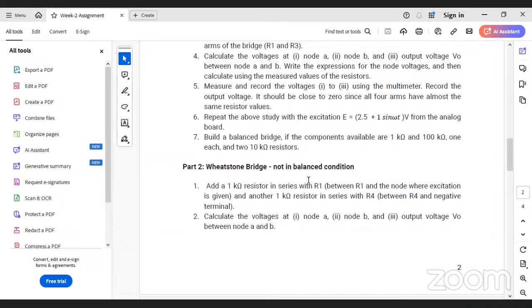If you add a sinusoid to a 2.5 DC, the lowest point will be 1.5 and the maximum point is 3.5, right? It will add and subtract one, like that. I'm not getting in Pixel Pulse where to give that, how to move the sine wave up and down. Okay, it's zero. Okay, 0 and 2.5 volts is mentioned along with the frequency. So there you can change it. Okay, one minimum point and maximum point. I think you just have to figure out how to work it. Okay.